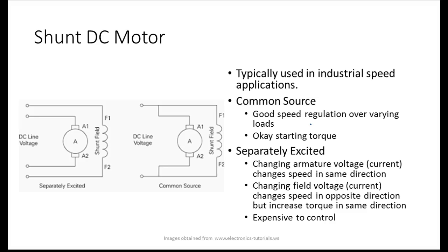Well, the spool gets bigger, the torque changes, right? It takes more torque to turn it, but you want it to run at the same speed. So they use these separately excited motors up there. Most of the DC motors out of US Steel were separately excited because they were just easier to control.